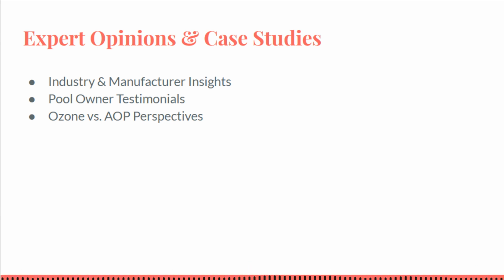and that their chlorine usage dropped roughly in half, also advising to adjust pump speed to avoid any ozone bubbles. Another case study from an indoor commercial pool that installed an ozone system saw combined chlorine levels drop to virtually zero, and patron complaints of odor and irritation disappear. A dramatic illustration of ozone's impact on chloramines. While residential pools are usually less extreme, the same principles apply.